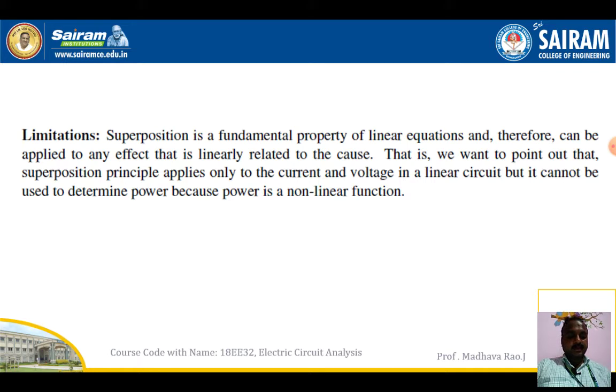Limitations are very important for your exams. Sometimes they will ask you to write the limitations of the superposition theorem and explain the superposition theorem statement. Superposition is a fundamental property of linear equations and therefore can be applied to any effect that is linearly related to the cause. So only for linear circuits can we apply this superposition theorem. For non-linear circuits and non-linear elements we cannot apply the superposition theorem.